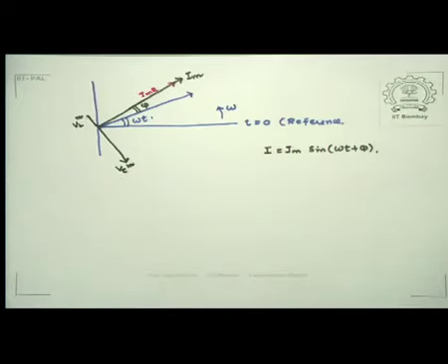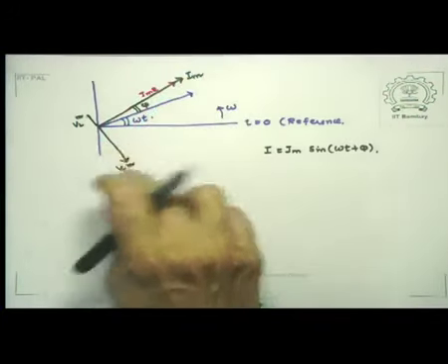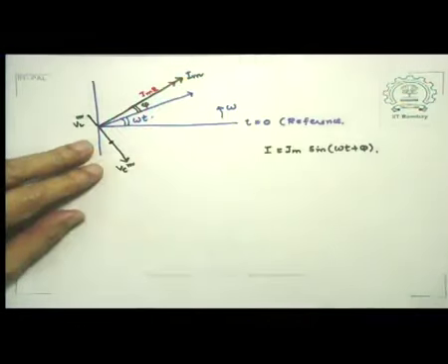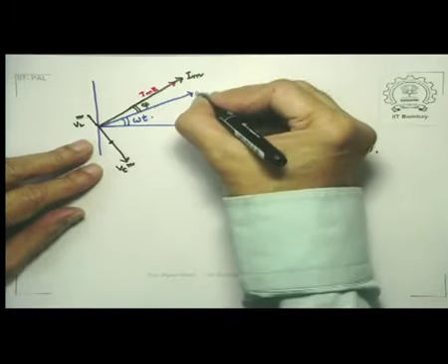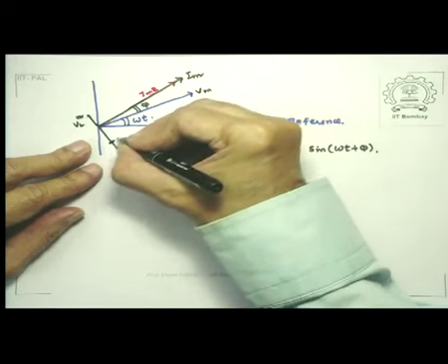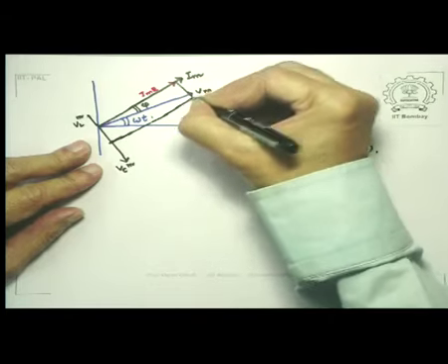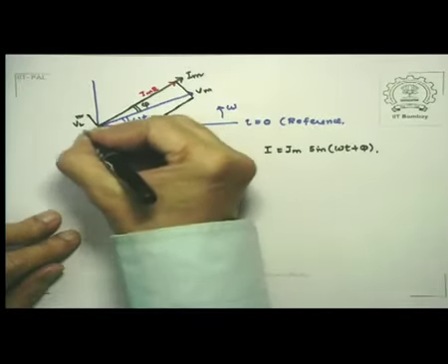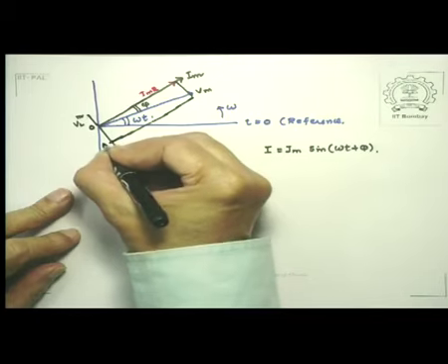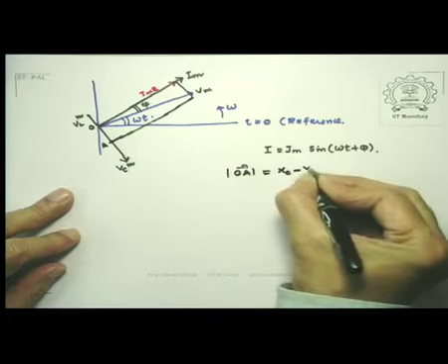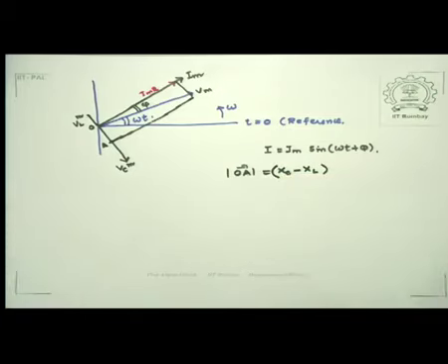Since VLM and VCM are oppositely directed, there will be a net along VCM where the capacitive reactance is larger than the inductive reactance. So you subtract the two and put it somewhere here. Now this Vm that we have drawn, if you complete this rectangle here or parallelogram here, so this amount from O to, let's say A, OA magnitude is XC minus XL times current.